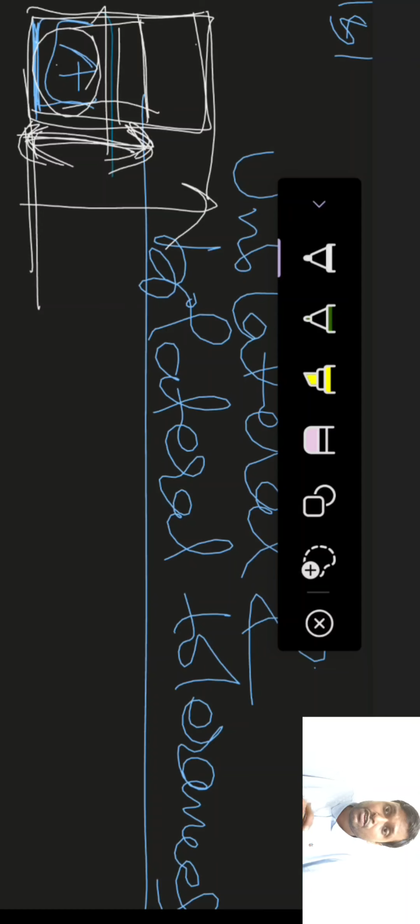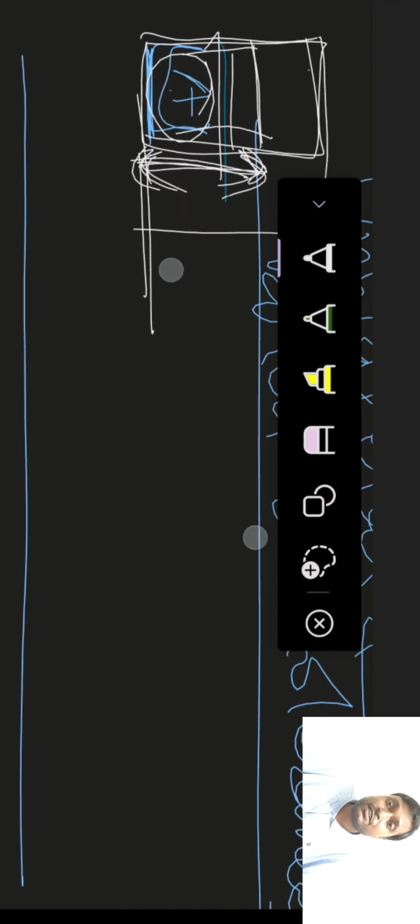So by applying the fundamental deviation, we are only fixing one of the limits. That may be the maximum or the minimum. Here it's the minimum limit, or you can say the lower deviation.